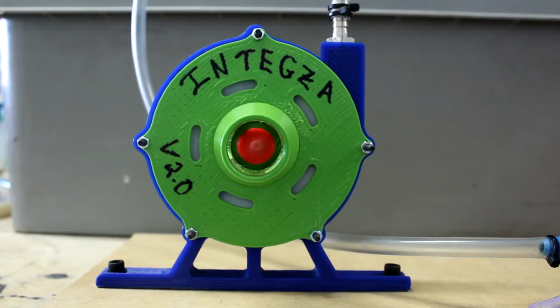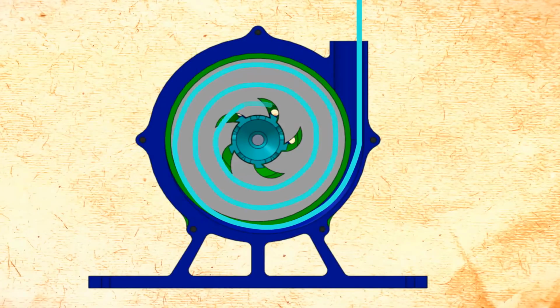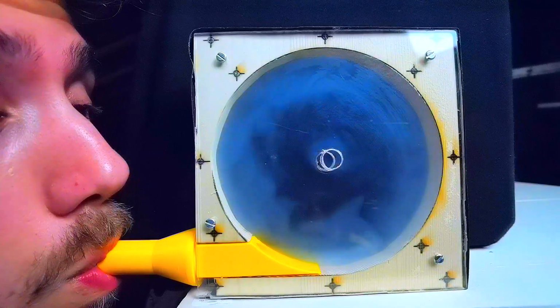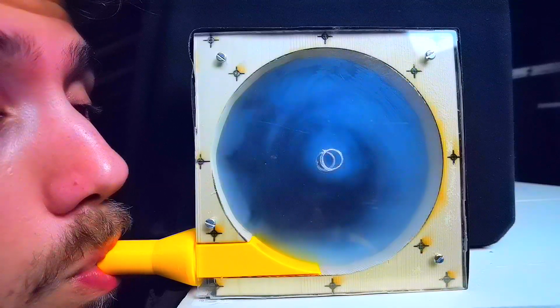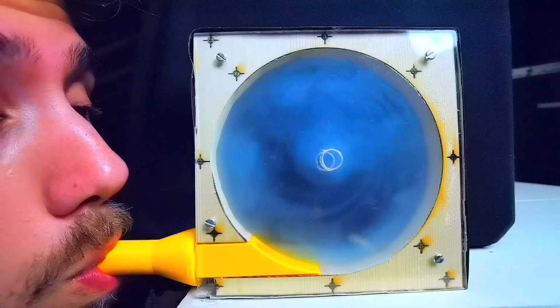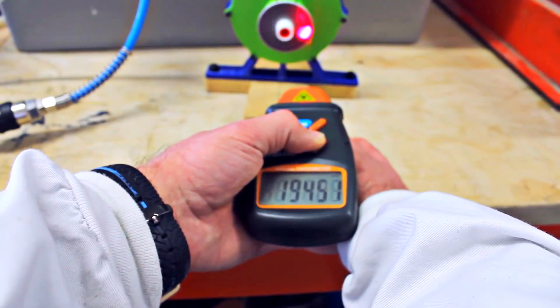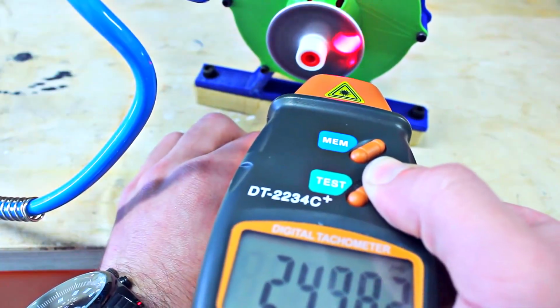In an ideal scenario, we would have a tight spiral that fills the entire casing and goes through most of the disk's surface, but that doesn't happen in this case. In reality, the fluid follows the curvature of the casing only in the outermost perimeters of the enclosure, and then collapses in the shortest distance possible to the center. This lowers the efficiency of the turbine considerably, and to fix that it's necessary to use a better casing.